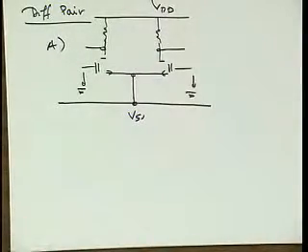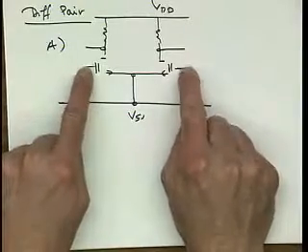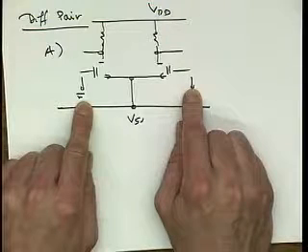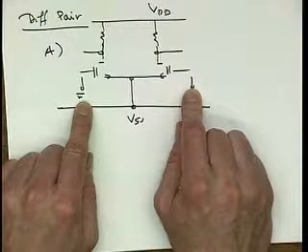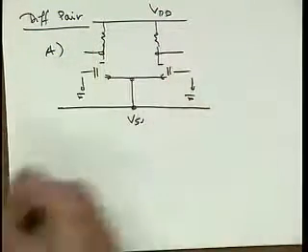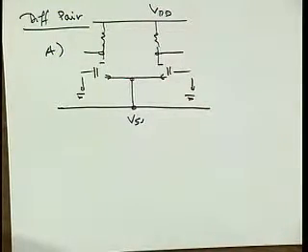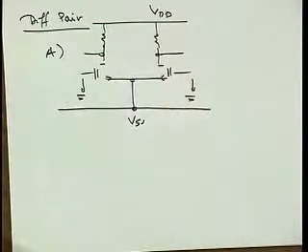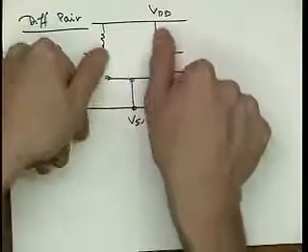Well, what does it mean, common mode rejection ratio? It means that I'm moving both of the inputs up and down simultaneously by the same amount. Basically, I short them together. And how much differential signal do I develop here then? What's the differential signal that appears if I move this up by 1 volt? 0, right? As long as this thing is fully symmetrical.